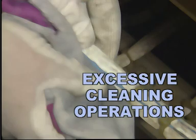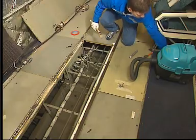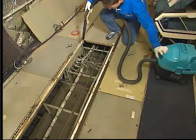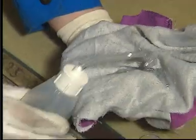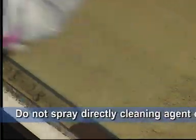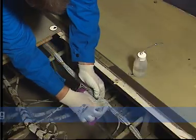Excessive cleaning operations. Overzealous cleaning or inappropriate cleaning without proper preparation and tools, such as a soft brush and vacuum, may result in wiring degradation. During in-depth cleaning operations, use a clean cloth. First, spray cleaning agent on the cloth. The cleaning agent must be in accordance with the recommendation of the Airbus technical documentation.